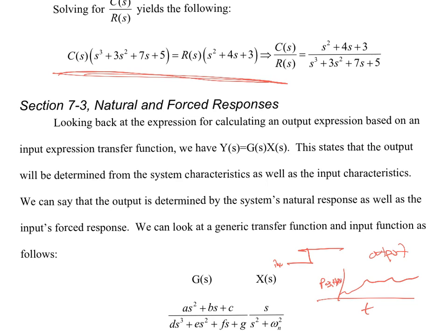What would you do? This is an equation, isn't it? In Excel, you can have Excel solve for an equation that will model this. I think Excel can do up to a seventh order equation that can replicate the function. So Excel can actually calculate what the function needs to be to do that. So these programs or these systems called ProTuner, all that stuff, that's essentially what they do. They bump it and they just monitor the time and the output, and they can give you a pretty good representation of the system. So if you can't or don't want to actually come up with a process, you can actually do that pretty efficiently.